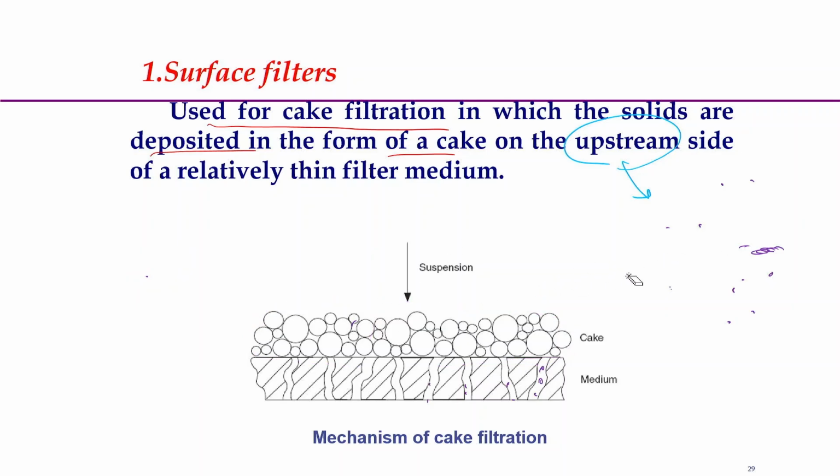So, this surface deposition of the cake helps in increasing the filtration efficiency, although it increases the pressure drop to some extent, but after a certain time we can remove the surface cake that has formed.